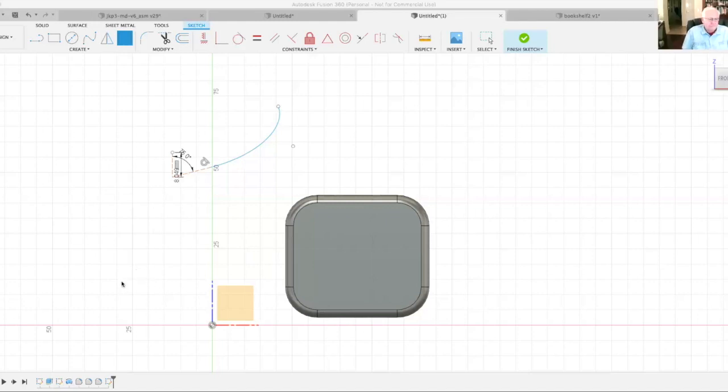Okay. Sorry about that, Mark. You wanted to say something? I was just going to point out that Fusion has a lot of settings for slicing. I've only used the basic ones, so that would be something to get into in advanced. Actually, what I find easier if you're going to do advanced things is to export your STL and use Prusa Slicer. It's more intuitive, but I can definitely show you how to go straight from Fusion with the basic settings. Okay, good. So we've got a couple of good topics coming up.